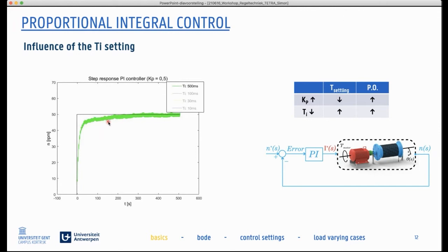And what is the error here? Well, you see a so-called immediate response here. And if you see something immediately happening, that will be due to the proportional term in your controller. Then after that immediate effect, you have a slowly building effect. And a slowly building effect is very typical for an integral controller. The integral needs time to sum up all the terms you add to reach the certain value of current to drive the machine. So actually what we need here is a quicker integrator. We need an integrator that is quicker.